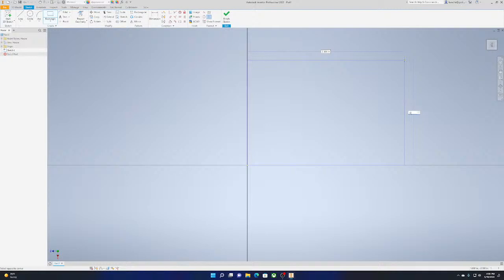So we'll write 1 inch, or you can just type in 1, and you can see now that it's locked, and I can't change my height any further. It's locked when I hit 1, and I can do the same for the other and then press enter, and now we have a box. I'll redo that in case it was too fast: rectangle tool, go to the origin, type in 1, then tab to go to the other one, not enter, type 1 again, and then enter. So you have this little cube.